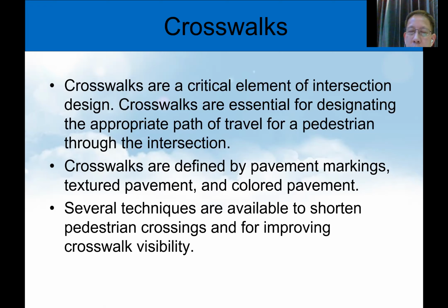So nowadays, we want to give more consideration to vulnerable road users, which include pedestrians and bicyclists. So we want to have a good crosswalk for them. A good crosswalk, in my opinion, is well lit, gives pedestrians the right to cross, and affects the traffic flow very minimally, to let them move as smoothly as possible.